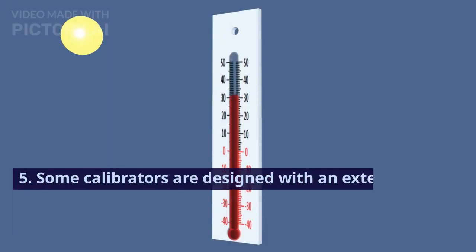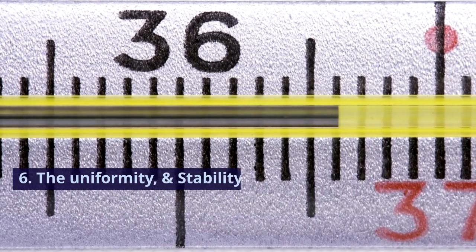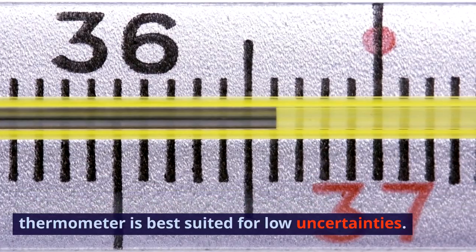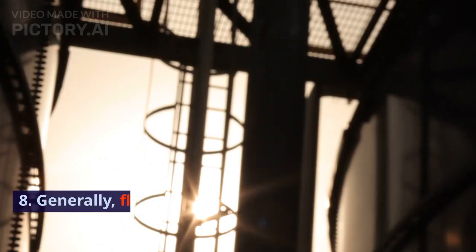5. Some calibrators are designed with an external thermometer system for accurate measurement of bath temperature. 6. The uniformity and stability of temperature baths are so good that a high-grade thermometer is best suited for low uncertainties. 7. Temperature bath calibrators are more accurate with external reference sensors compared to dry blocks. 8.